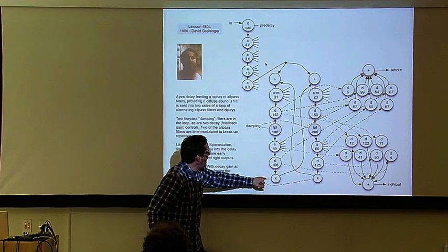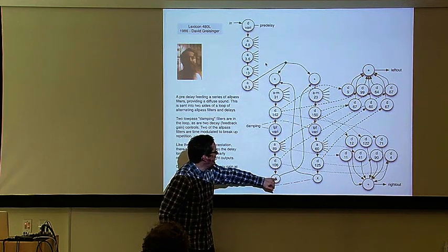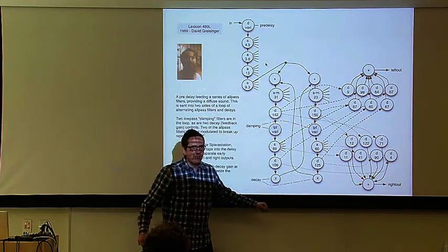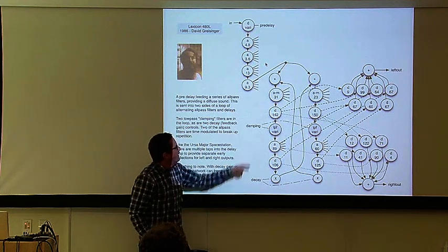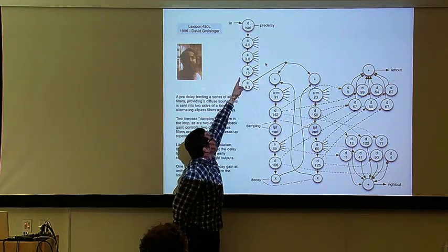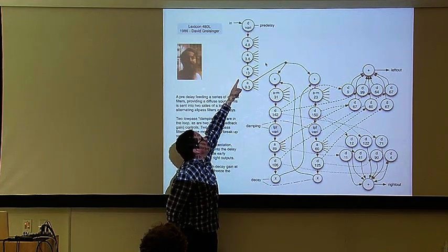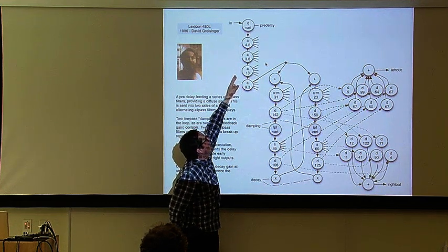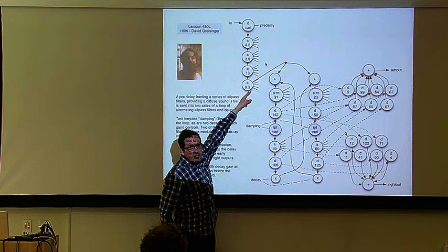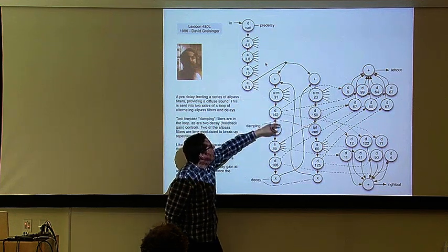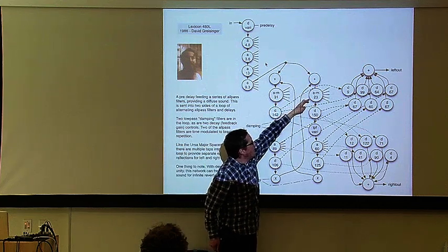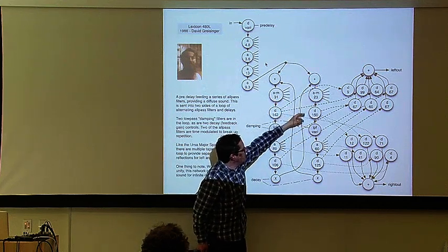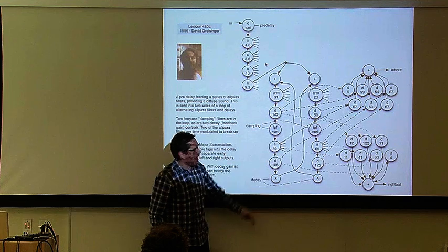If we put these decays at 1, we can sustain forever. But there are a few more things added here. The all-pass filters are now seen all over the place. We have a chain of 4 all-pass filters coming into the structure. We have all-pass filters in between every delay line. And so this puts all-pass filters in feedback.